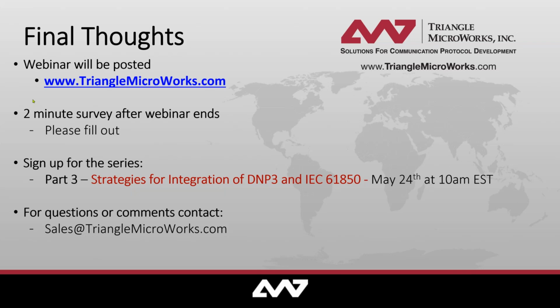Okay, so the CID file, and there was a similar question related to that I probably also just answered. The question was, can we import a CID file in the process as well, other than just an IID and an ICD file? So the difference between an IID file and a CID file is an IID file just describes the instance of the device with all the data model, all the configured values of parameters and the configured communication.